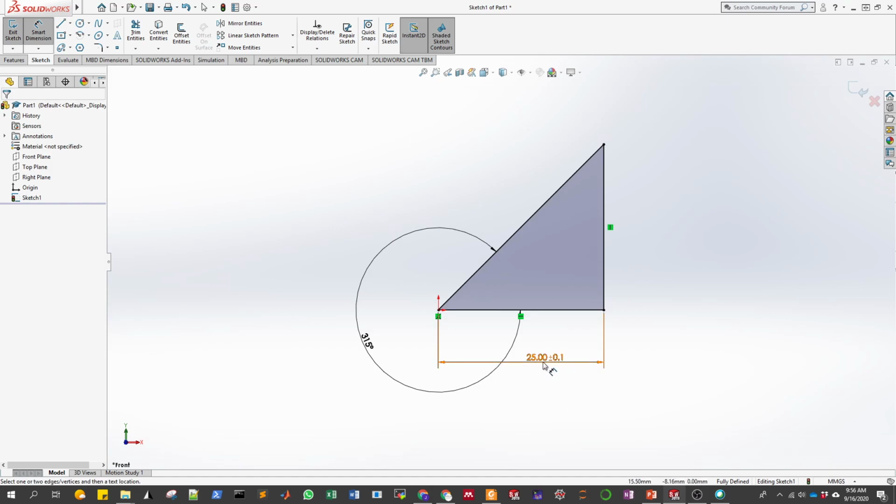And basically when you do a blueprint like this, you are defining that the length of this triangle is nominal 25, and then you have a range in which you accept an error for this length, because you know when you are manufacturing things, it's not possible to have super precise measures.